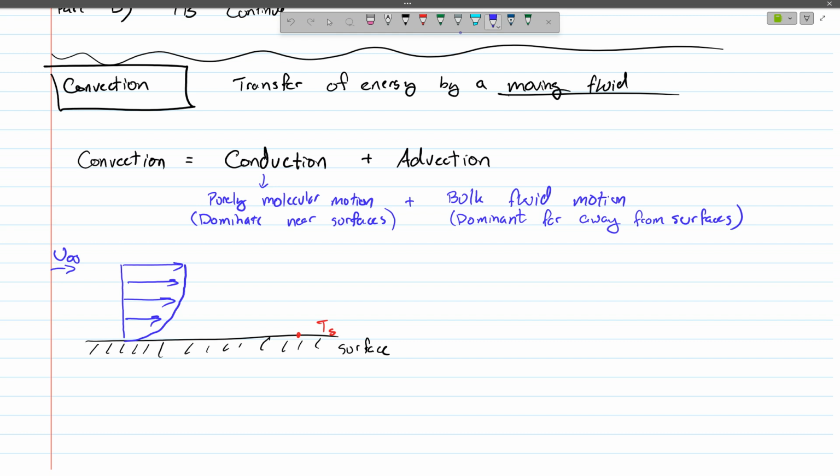In heat transfer, we're going to qualify this a little bit, and say, hey, this isn't just any old boundary layer, this is known as the velocity boundary layer. There's that region of change between the velocity of the surface, in this case 0, because fluids have to have continuity of velocity, and the free stream velocity, producing this continuous gradient.